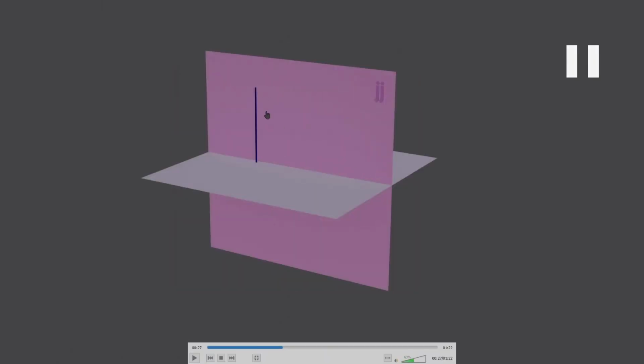We'll see that when you look from the front, and when you look from the top, you can see that it is parallel. Now we'll see the top view. See that in the top view you just see a dot here, right? That is because this line was parallel to the vertical plane and perpendicular to the horizontal plane. If a line is perpendicular to the horizontal plane, when you look from the top, you don't see the bottom point, you see only the top point. You just see it as a single point, since it is perpendicular to the horizontal plane and parallel to the vertical plane. Okay, now let us see the three-dimensional view and then how we draw this. Yeah, this is the three-dimensional view.